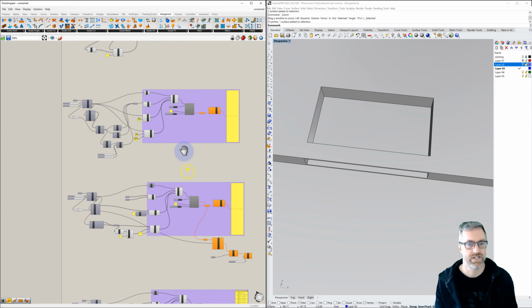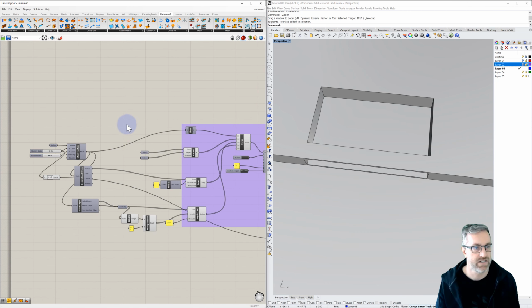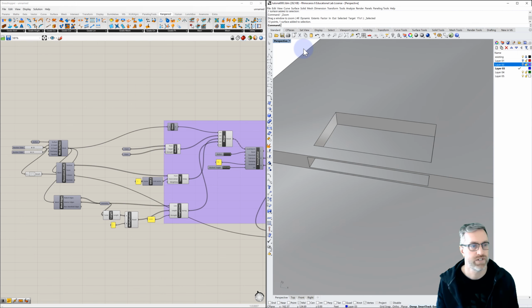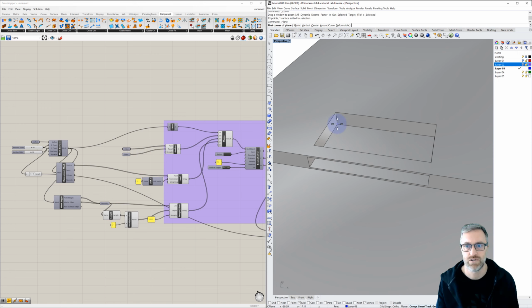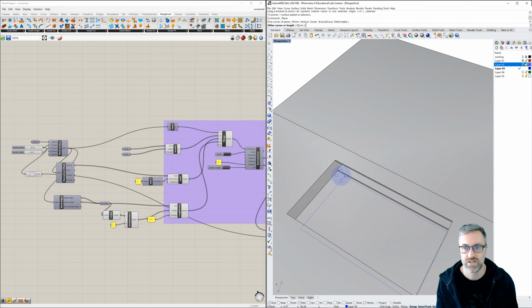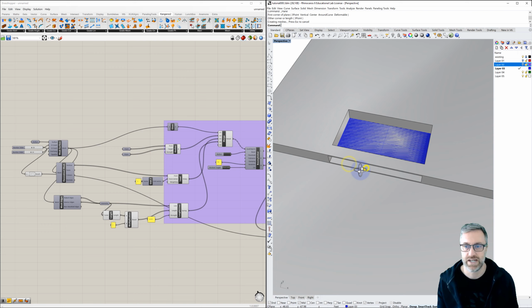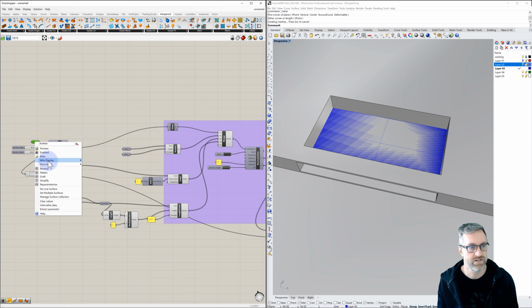Okay, so we have our last example here. Let's start the same way and let's create a surface. We could even probably start with a mesh, but it seems like it's much easier to draw a corner to corner surface. And because I changed everything to vertex before, I'm going to turn on endpoints so I can select that. Now we've got a surface at the floor of the courtyard. Let's set this surface with our surface container.